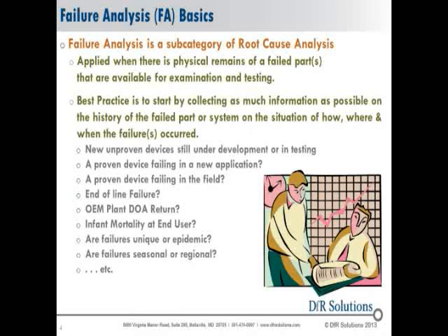Another important issue is, are these failures unique? Are only a few parts affected, or is it epidemic? Is it happening all over, many, many times? And are the failures perhaps seasonal or regional, where we're seeing different weather trends or usage techniques in different parts of the country or climate? These are some of the very useful items of background information that are very valuable sometimes when you're starting a failure analysis.